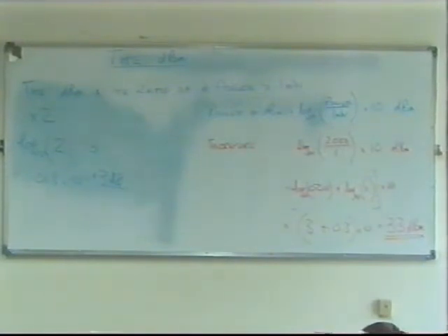Sometimes we found it at 40, and we said no, make it 60. So you said the gain will only be plus 3. Is it effective? It depends. It is watts you're talking about. Then if you change it from 40 watts to 80 watts, it's a 3 dB change. It's not that much. And we get a problem sometimes with heat. Yes, that's true.